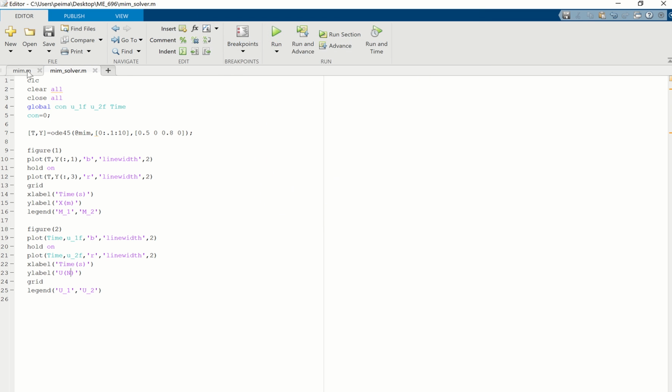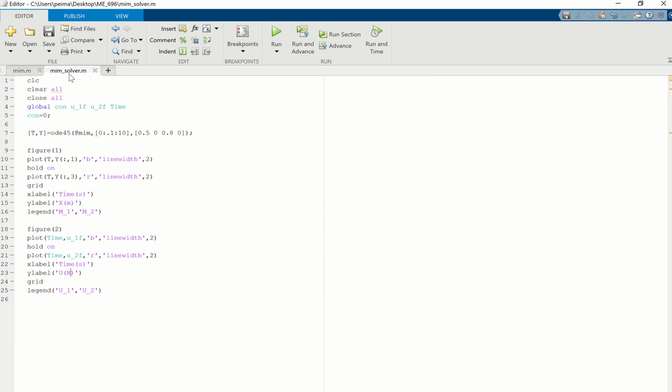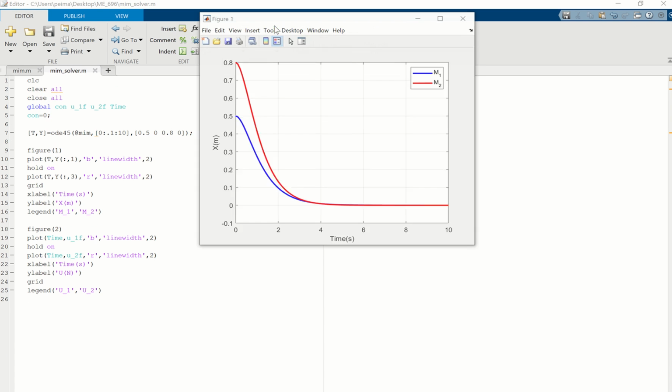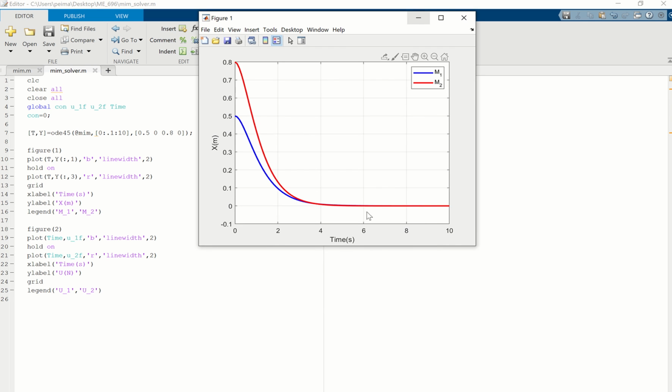Now if I change, if I say, you know what, I don't want to have the underdamped system, I want to have desirable poles at -2, -1, -1.5, -1.5, and -1.7, meaning that I only have real parts with negative eigenvalues or poles. So here we're going to get, right? See, guys? A completely critically damped system. There's no oscillation. There's no overshoot. That's right.